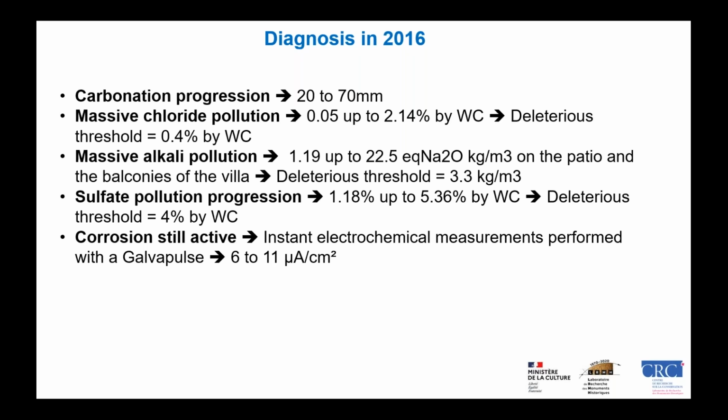We also had massive sulfate pollution with the progression of this pollution between the two periods of diagnosis. It was up to 5% by weight of cement, with again a deleterious threshold of 4% by weight of cement. And the corrosion was still clearly active.